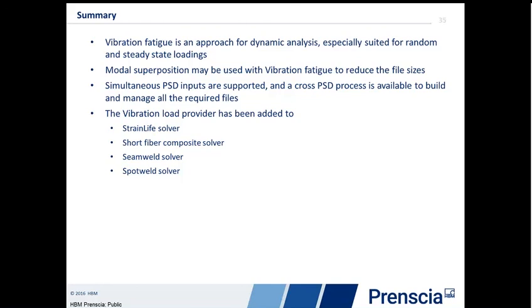Using vibration fatigue, we can simulate what we do on a shaker table with basically a sequential set of PSDs where we sum up the damages. We can also apply PSDs simultaneously, and we have built into the software flows that allow us to generate all the inputs necessary to support that multi-PSD analysis. And then finally, at 12.1 and 13, we are introducing the vibration load provider into whole new engines. And we talked about the fact that we have strain life, we have the short fiber composite, seam weld, and spot weld.